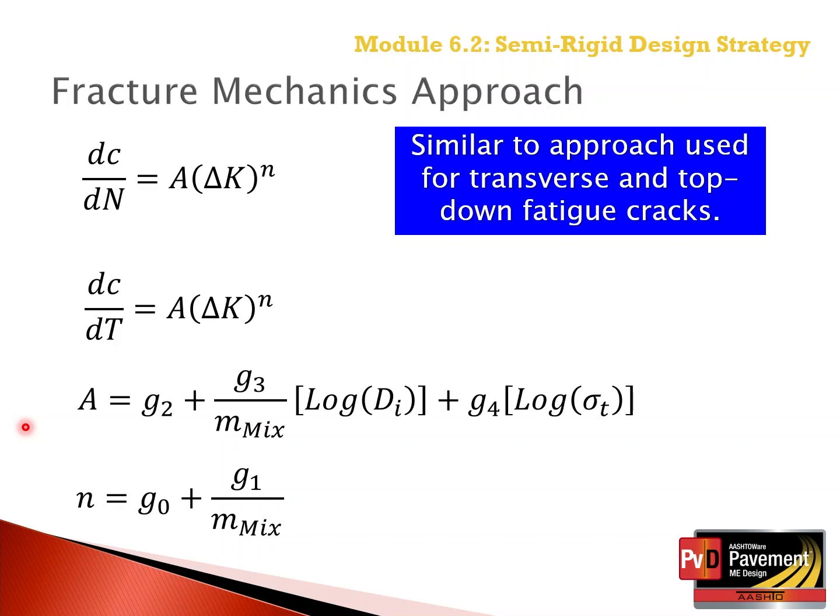So the fracture mechanics approach basically divides the computations of the stress intensity factor into two parts. One is related to the incremental application of wheel loads, which is more similar to top-down fatigue cracks using fracture mechanics for flexible pavements. The other is used for incremental increases in crack growth related to thermal or temperature cycles, the difference in temperature cycles.